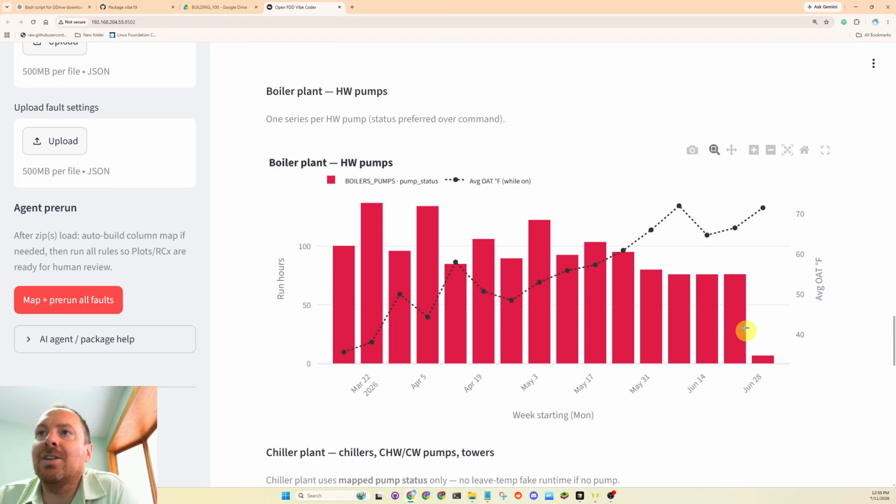I can also see here that for a variable volume air handling unit system, they must drop the boiler system. In theory, if this was a residential system, you'd never be running a boiler in the summer, but sometimes by design, I think VAV systems can require a boiler to be running even in the summer, and that's for dehumidification purposes.